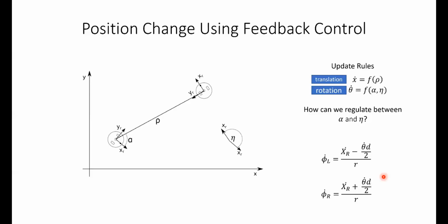So I can get whatever values I want out of these inverse kinematics equations, and you'll get large values, right? Much larger than your wheels can actually turn in one iteration or 32 milliseconds. And so in the lab, what we're doing is we're figuring out what the relative speed should be by dividing the one by the other. And so that's why these lowercase r's disappear from us, because they're in both equations. And so if we take a ratio, those get canceled out.